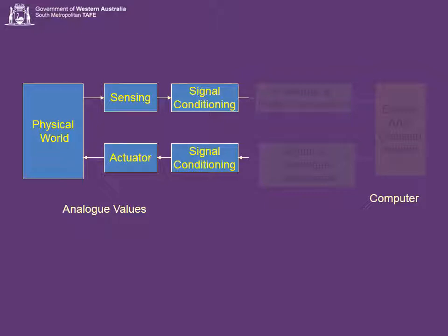We have the analog part of the system, which is the real world part of the signal system. In the real world, all the signals exist as real values, 0 to 10 volts normally, and things are really happening. In the real world, everything is measured in engineering units. That'll be degrees C's, watts, pascals, that sort of thing. They're engineering units.